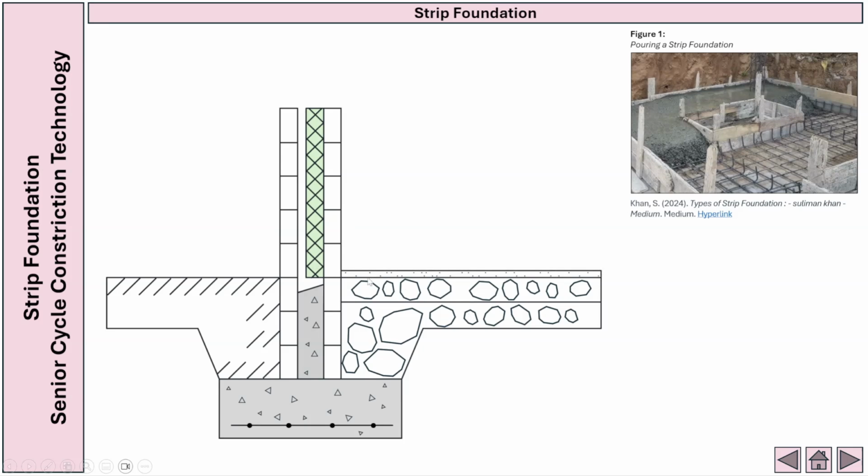The next thing we're going to do, we're going to pop on back over to the right hand side and we're going to draw up 40 millimeters or in this case 4, then bring it straight across here, and this is going to be our sand blinding. And we can tell that it is our sand blinding just by the few dots here dotted in and around. And you can mark that in your exam by dotting your pencil. With the hardcore as well, just draw in a few little rocks, just like this, circular rocks, just to show that it's hardcore as well.